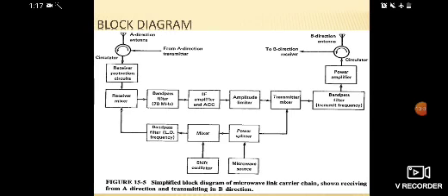Okay, and the next one is the band pass filter. So what is the use of the band pass filter? It is used to allow a particular band of frequencies, that is, the 70 megahertz frequency is going to be allowed. Other than that, it will be eliminated, it will reject that. And it is also used to eliminate the harmonic distortions.